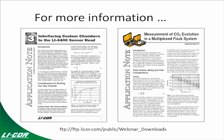And so there's a theoretical size limit, but there's also the actual sample material that you're trying to measure, and that imposes limits. But if you actually look at using a closed system for the 6400 or the 8100, that chamber size can be quite different. You can have very, very large chambers depending on the mixing you have within the chamber. That's right. With closed systems, we've seen chambers done that were several cubic meters in volume that had individual fans in there to increase the mixing. But again, it comes back to the sample material, and that the sample material is really what imposes the size limit. With a closed system, you go too big, you dilute the fluxes too much, and